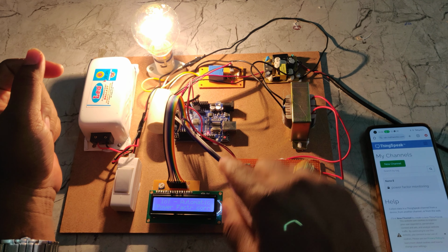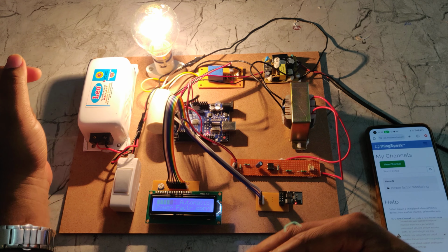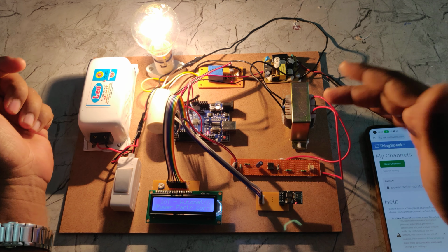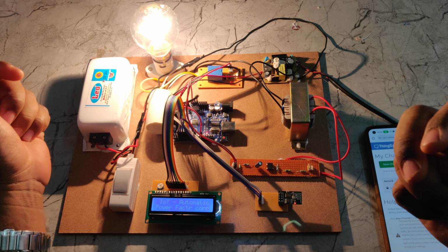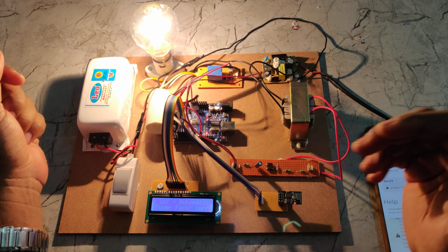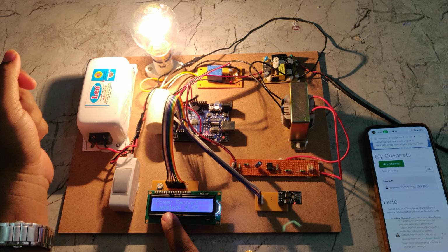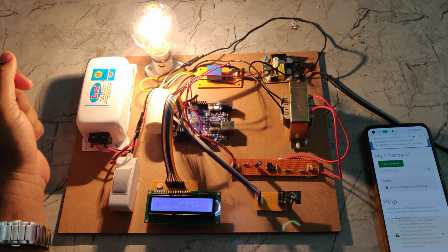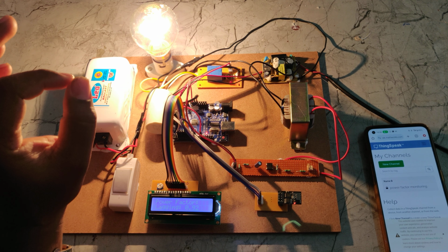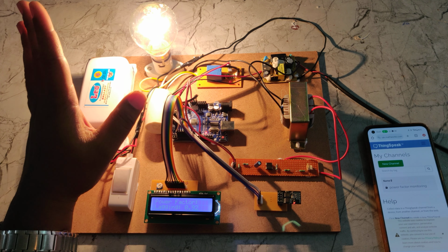Now if it hangs over there, you just need to reset, because the reset has to be done frequently. As we are using AC, there is a humming noise, and the noise will occur in the system. Right, now we can see the power factor lagging 0.92. It is normal, as we don't get the unity power factor in the whole world with only a resistive load.